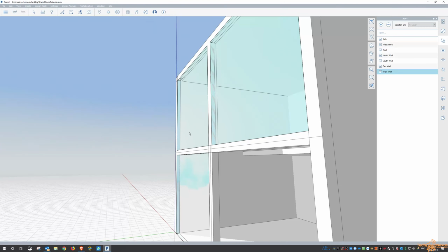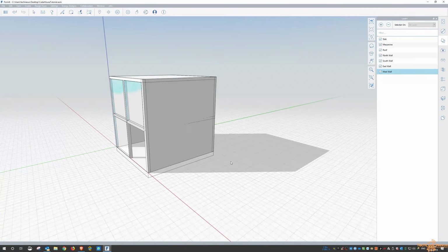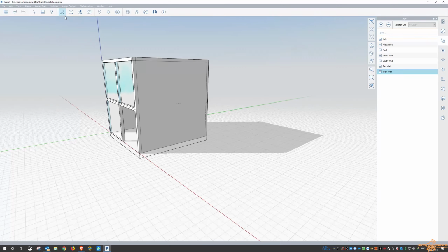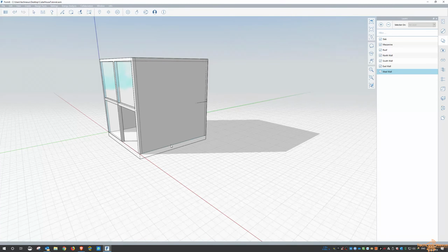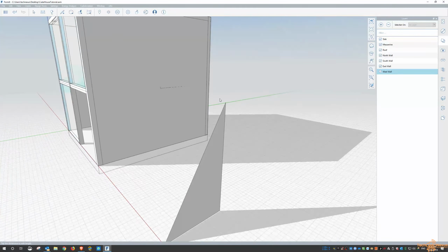Okay, so now the other thing I want to do is maybe throw in a set of stairs. So what we can do with this is similar to the sketch we did before with the window pane. We can do the same with the stairs, but I know that I want to go maybe, let's go sort of 3 meters in that direction, and I want to go 5 meters in that direction. Okay, so this is going to be the basis for the triangle of our stairs.